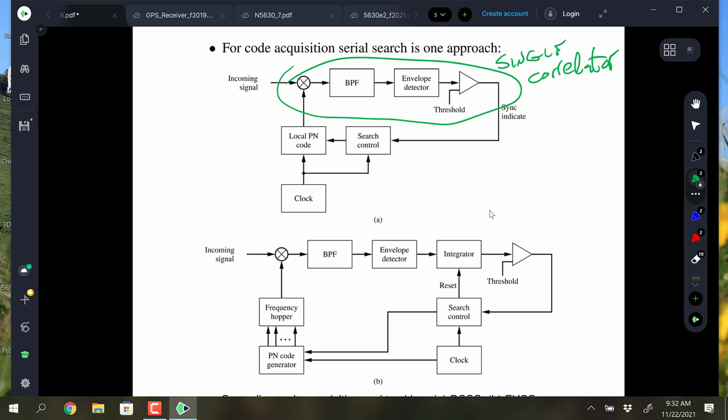And then if I were to get on an airplane and go to the other end of the country, where the ephemeris is all different because it's a different geographical location, turn on that receiver, it takes considerably longer for it to eventually lock onto all the satellites. It has this local memory: I just had it on yesterday, had it on earlier in the day, I turn it back on, it locks fast. Go to another location, it's got to figure that out.